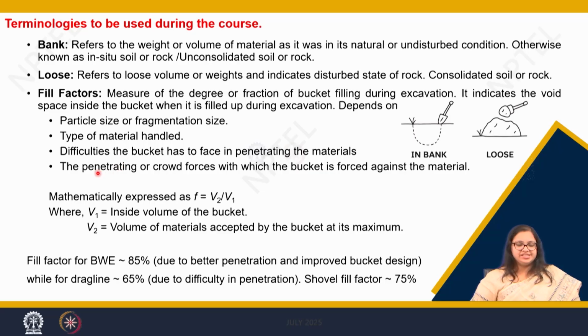Which explains the fourth factor, that is the penetrating or crowding force with which the bucket is forced against the material. Let's say there is a rock of certain strength and the bucket is crowded onto this face of the ore body. The force with which the crowding action takes place also affects your fill factor.